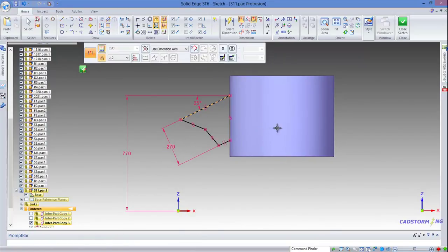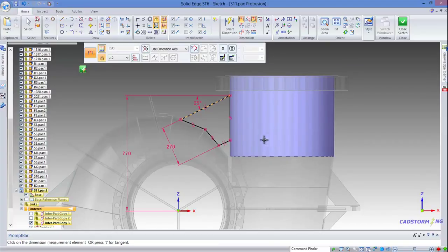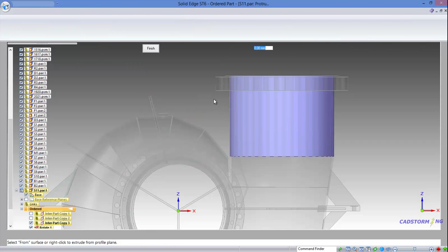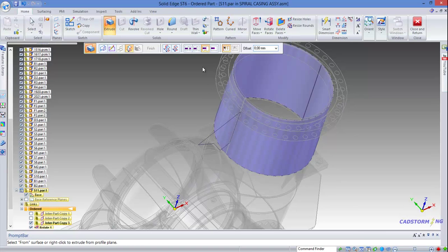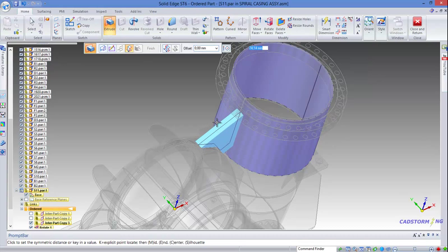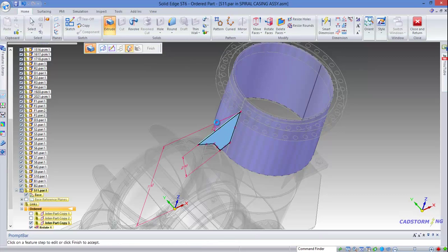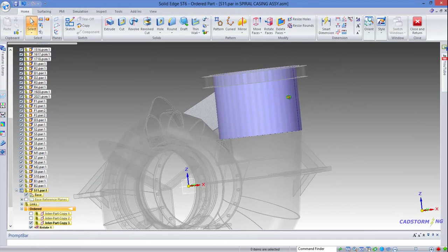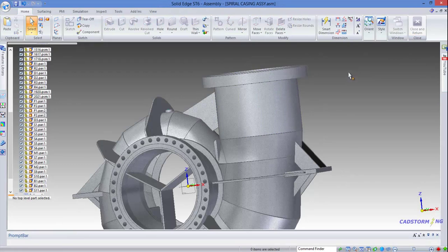and Ctrl Q to see how it is located. Looks good. Now we can just close sketch and we make sure that the extent is symmetrical, and we will use the finite extent option. So have 12 millimeters, and that's it. Now cancel. Okay, now close and return.